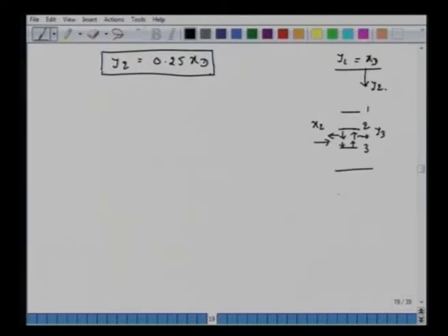So in this plate between 2 and 3, if you recall, we established the Q line. What was the Q line? We had an energy balance. Whatever energy is brought in here, we had an energy balance between the two streams of vapor and the liquids here. Alright, so now what we are trying to do is extend this operating line for the stage just underneath 2. So we started from xt, then we got y2. Now we will write down the expression for y3 and x2.